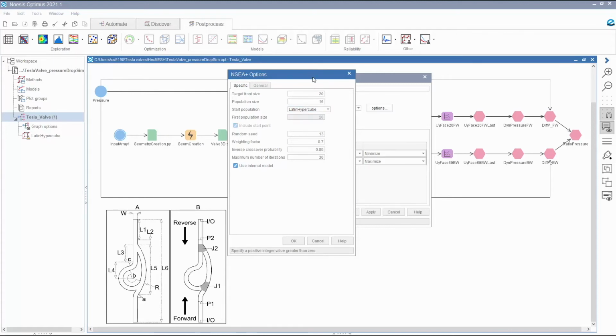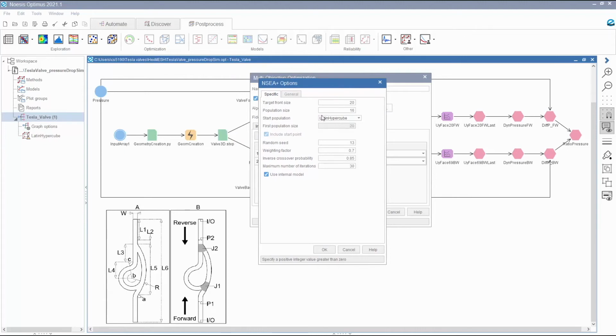So the multi-objective optimizer will define a model based on the starting population, and it will guess the candidates for the next population according to this model. After calculation for each population is completed, the model will be updated. So for the next iteration, again, the 16 candidates will be according to the new updated model.